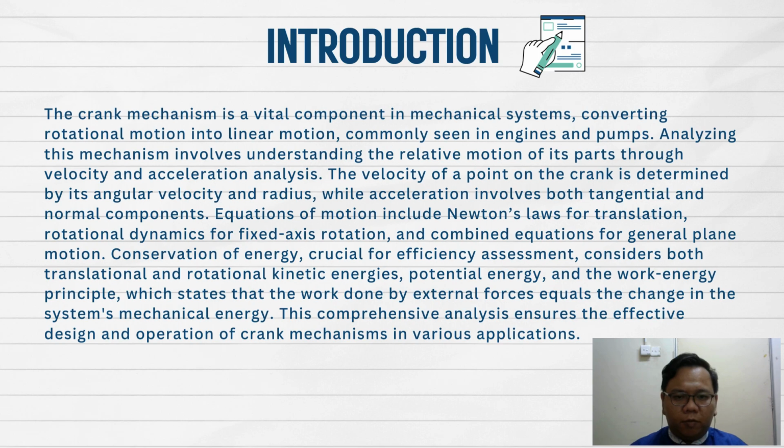The velocity of a point on the crank is determined by its angular velocity and radius, while acceleration involves both tangential and normal components. Equations of motion include Newton's law for translation, rotational dynamics for fixed axis rotation, and combined equations for general plane motion.